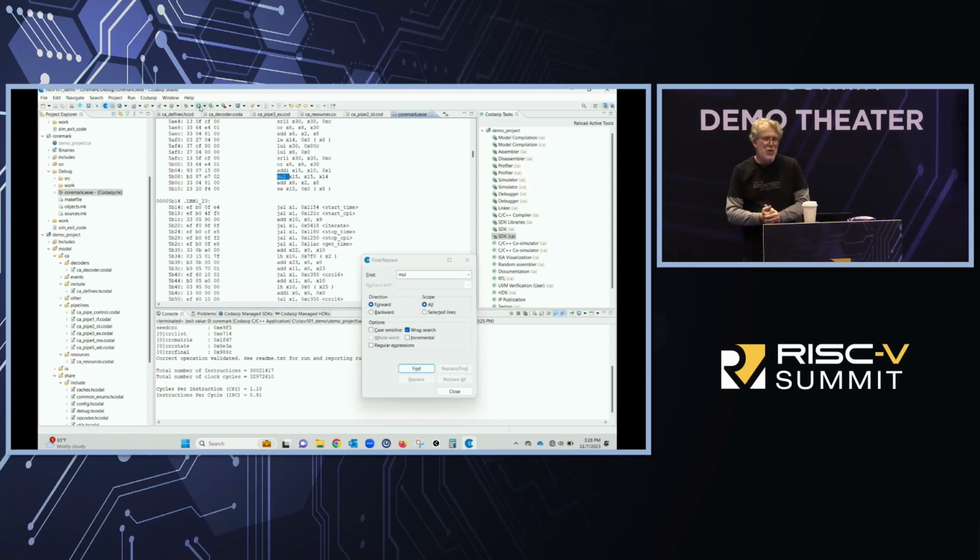And we're going to do a MAC instruction, a multiply accumulate. Now, if you think of multiply accumulate, I have 3 source operands. My two operands will do my multiply, and then my third, which is my accumulator, right? And then, of course, I'm going to assume my accumulator is also my result register.